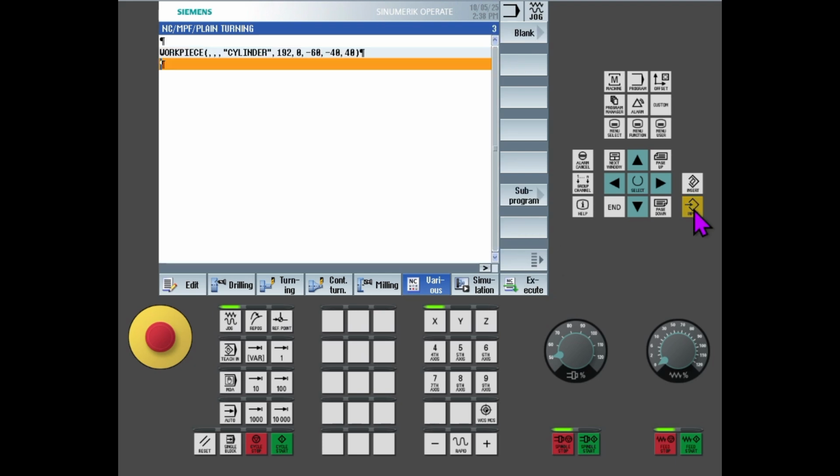After that, press input, then write down the G codes which are available for the pre-operation commands. The first one is G90, activating the absolute mode. Then you write down G71, activating the metric mode. Then write down G95. G95 is your feed in mm per revolution.